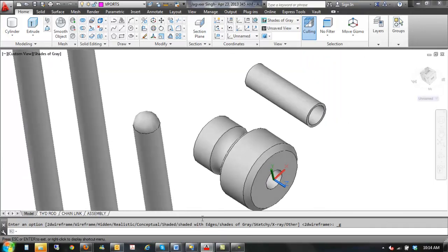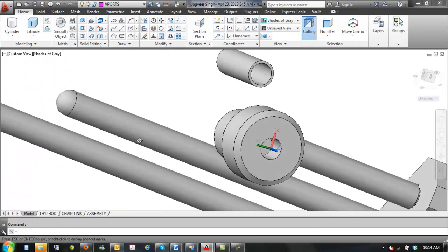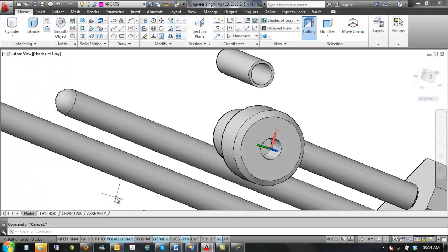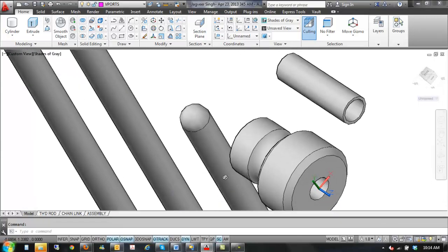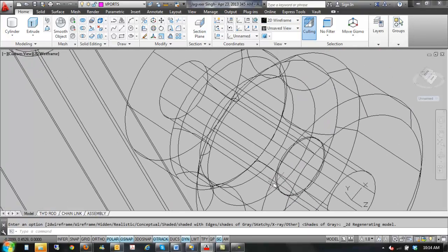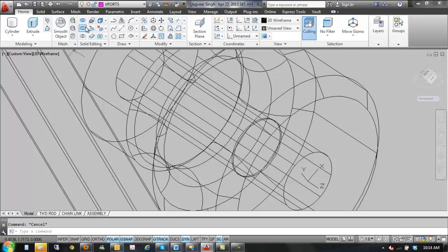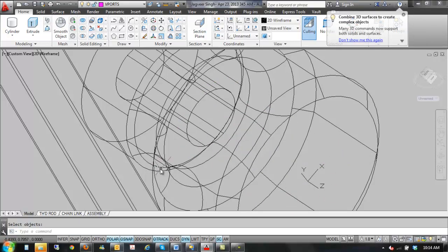No, the hole doesn't go through. Tell you what we'll do. Actually, this makes it a little easier to get rid of that geometry in there. I'm going to put a cylinder on the end here, just a little bit bigger and a little deeper than that object. And we'll do an add. So this will add together. That filled up the hole.